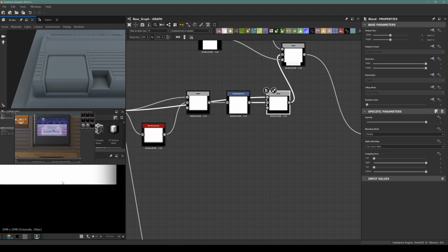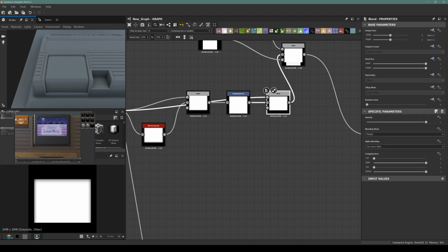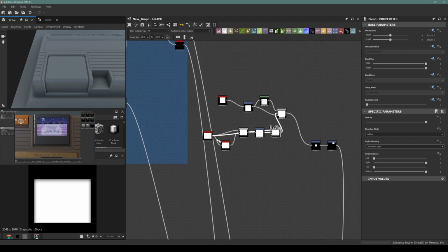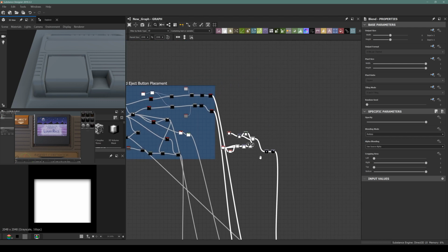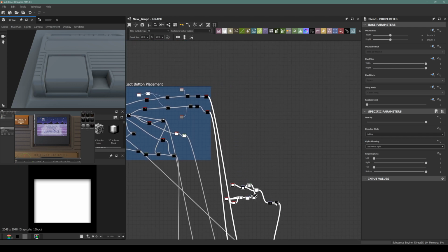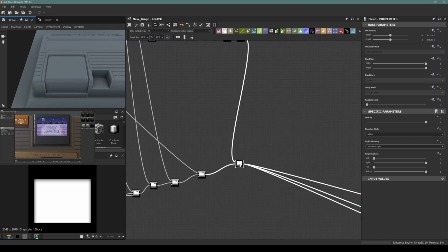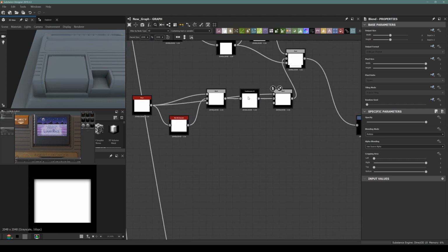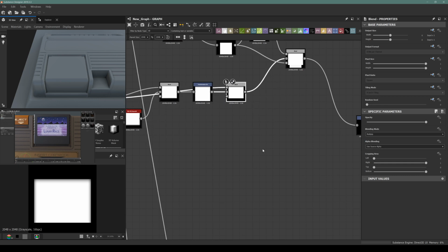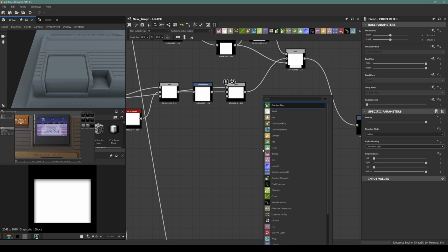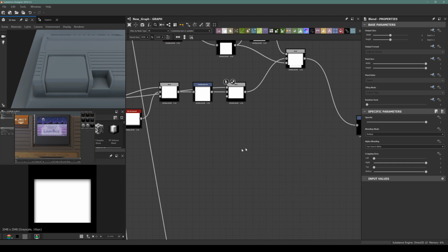Now we need to adjust the label area here and the other gripping parts or details on this surface. So we are having this on the case. So I will use, let's start by creating the label. I will use a shape node.